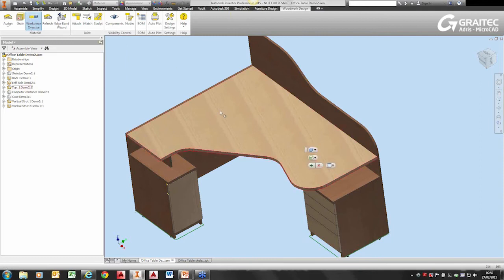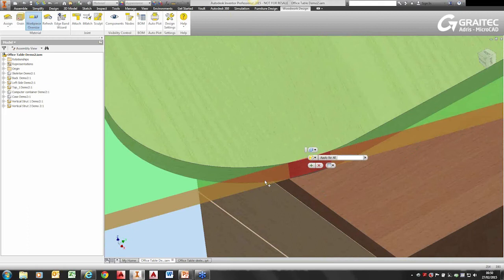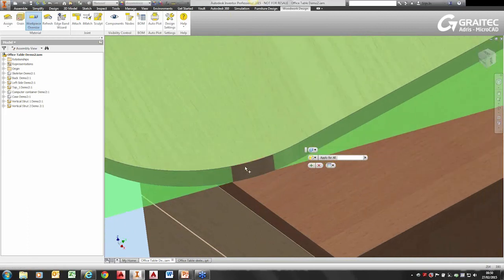If I select that, it automatically assigns it, and you can notice that I lined up the shape with the grain direction. So that's going to meet it perfectly. However, you do want to have maybe some oversize to allow for the machining, otherwise you're going to get probably a not very nice finish around this edge.